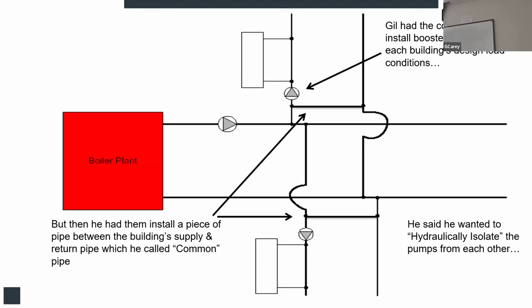And they turn on the pumps. They turn the boiler temperature up a little higher. I'll explain that later. But they increased the 200-degree water that they talked about to a higher number. And as this pump's pumping along, a certain amount of flow was going to be directed into this building. This pump was sized for this building's load. Now all of a sudden this pump could give the appropriate flow rate, the velocity, to get the pressure drop at that monoflow, so flow would go through. All 10 buildings work. They put in these common pipes. They put in these smaller booster pumps for the buildings.